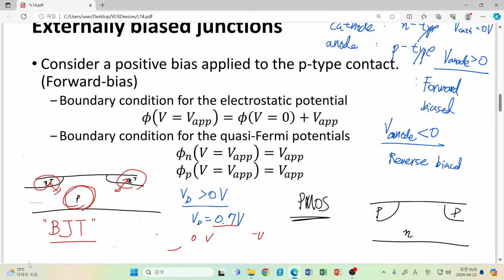However, in the case of MOSFET, this current path is not a desirable path. The only desirable path is just following the top surface between silicon and oxide here. However, if we activate this path, then actually the MOSFET can work as a parasitic BJT. This is a really bad situation, so we have to avoid this one. So please understand.